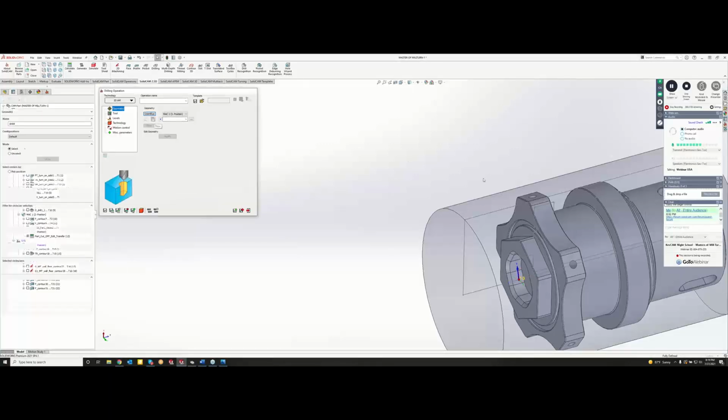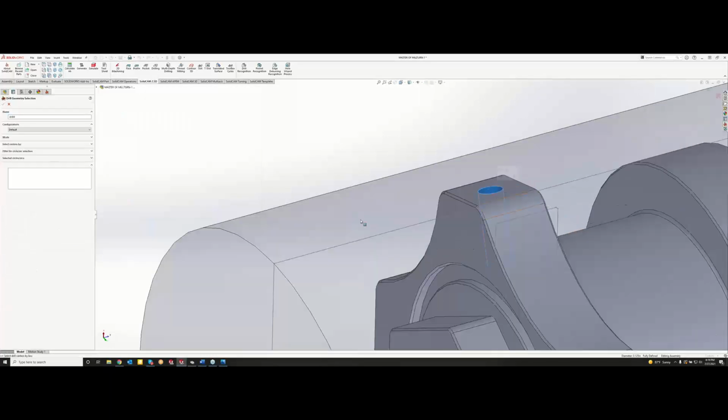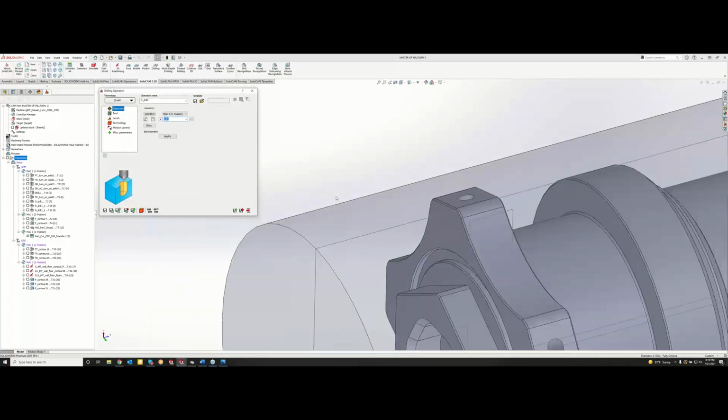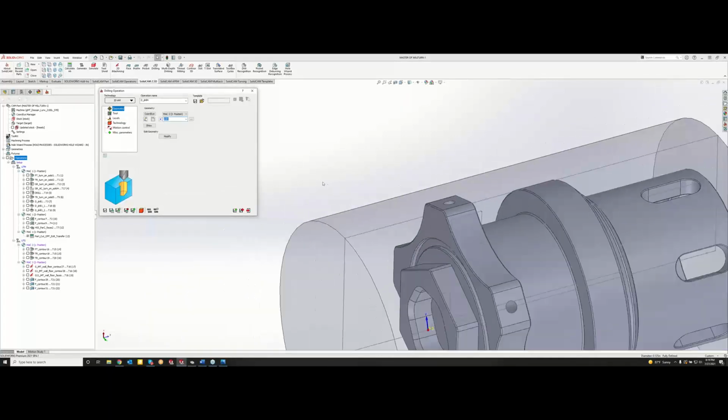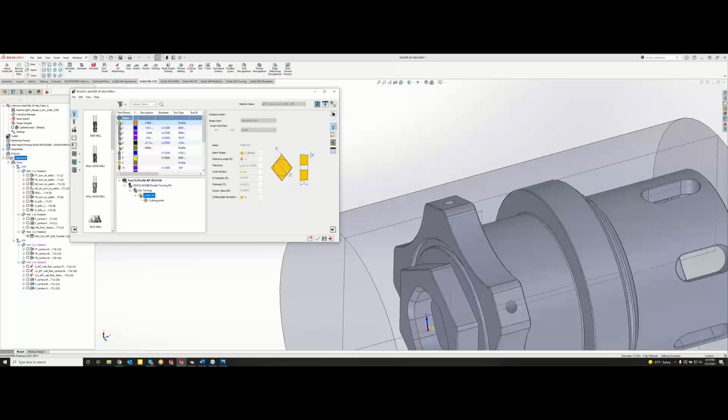And now I can grab my drill geometry. So there are 2 different ways of going about this. We can do this as drilling and then rotating the spindle, moving around, drilling again, and that's going to be around our 4th axis. But I'm going to show you guys a little bit different way of going about it here. Just, I don't know, thinking outside the box. So I need to grab my spot drill